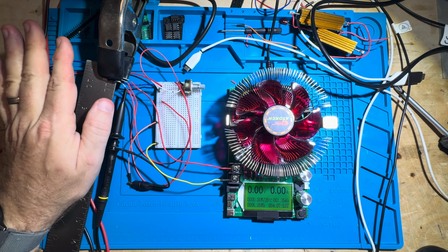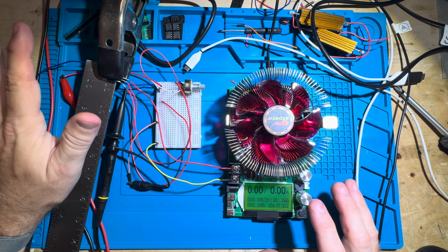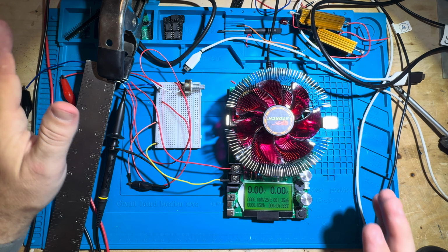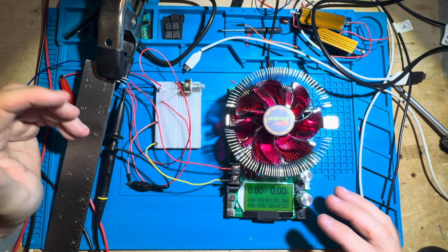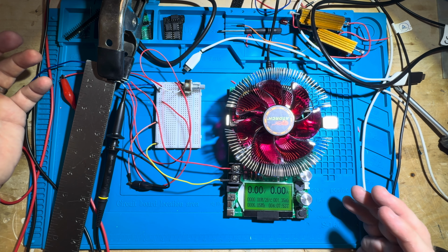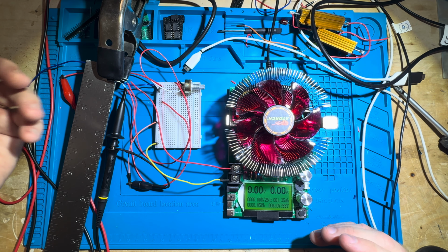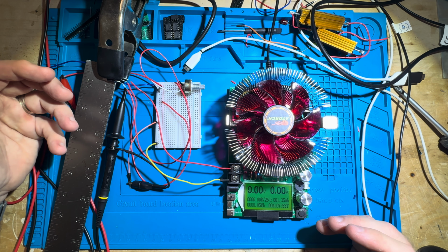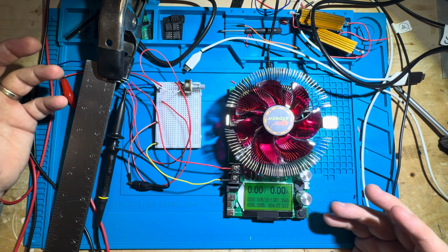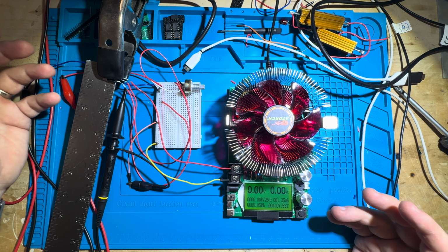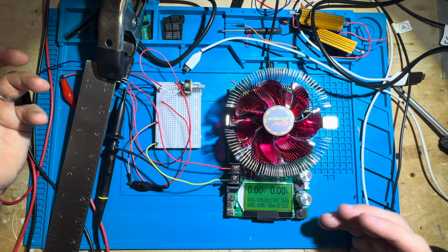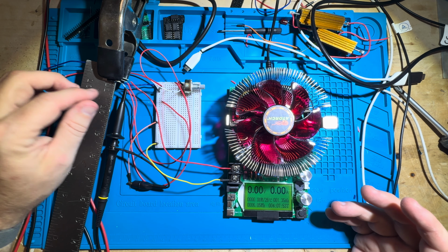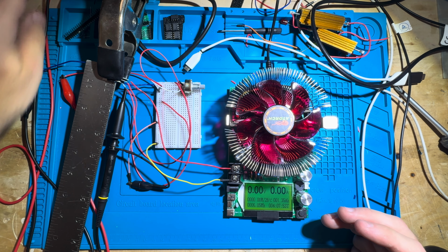But this is important because if I do drive significant amounts of current through here, even though it's a better, more adaptive situation, it's not a particularly efficient way of doing this. So we're still going to have the same issues that we had in the previous setup: we're burning off a lot of power, and that power is going to be burned off as heat, and we need a place for it to go without burning up our little MOSFET.